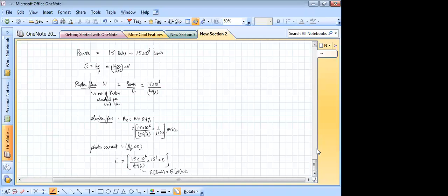Then it starts coming out at what time? It starts coming out at 20 divided by 2, or 10 seconds. So for the first 5 seconds there will be EMF induced. Then for the next 5 seconds the EMF will become zero. And then for another 5 seconds there will be EMF, but in the opposite sense.